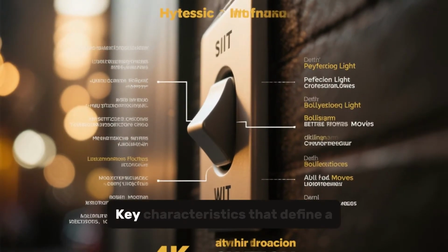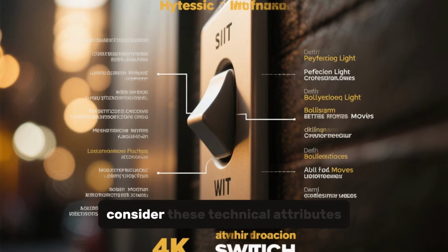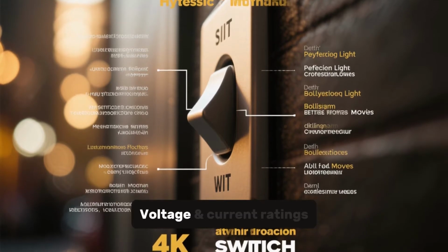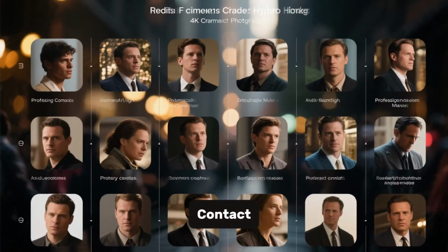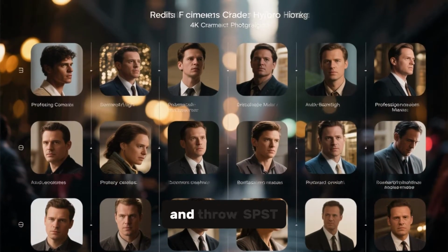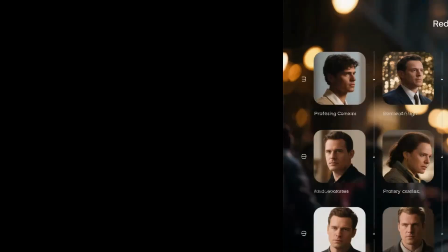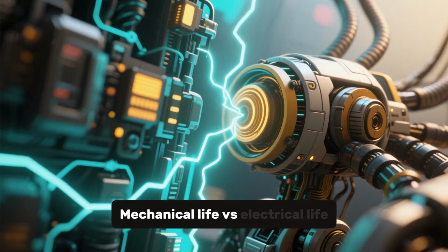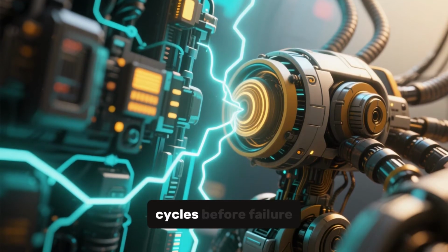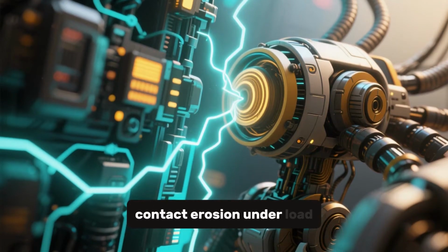Section 3. Key characteristics that define a switch. When you evaluate switches, consider these technical attributes: voltage and current ratings, the maximum safe electrical load. Contact configuration, pole and throw, SPST, SPDT, DPDT, etc. Determine how many circuits and paths are controlled. Mechanical life versus electrical life, cycles before failure. Mechanical wear versus contact erosion under load.